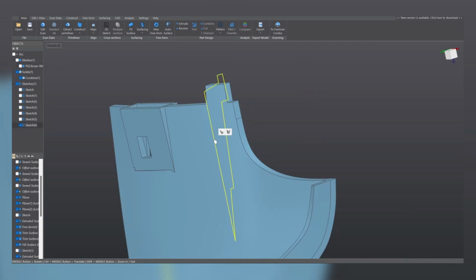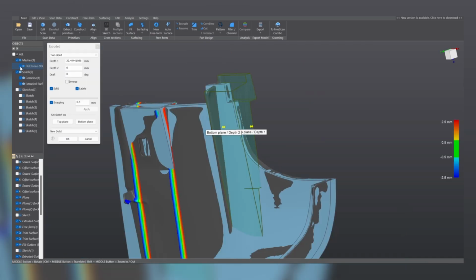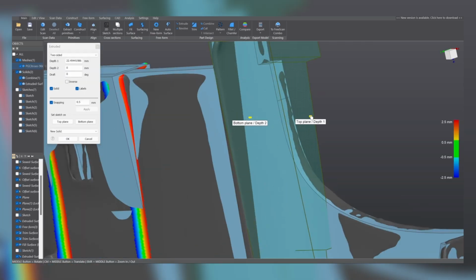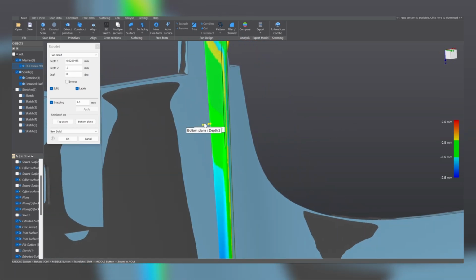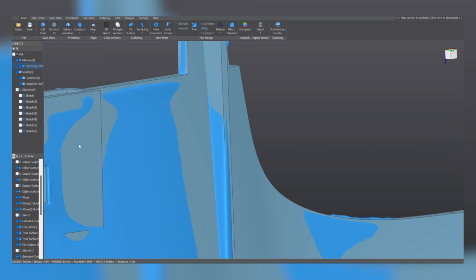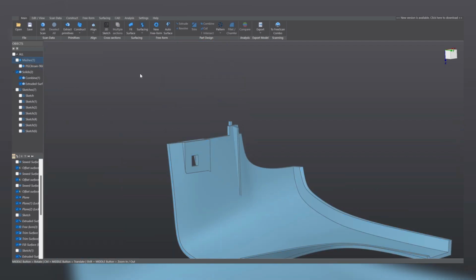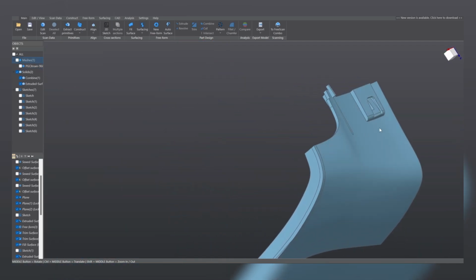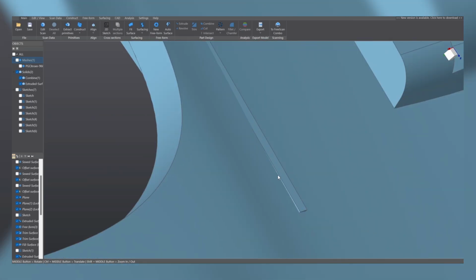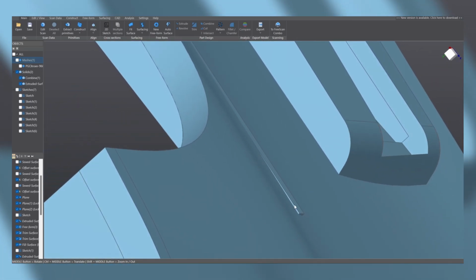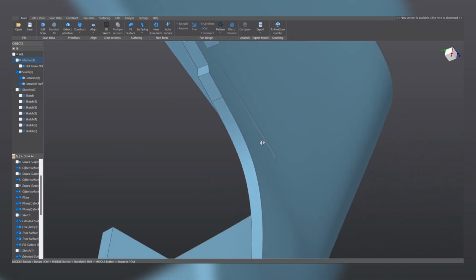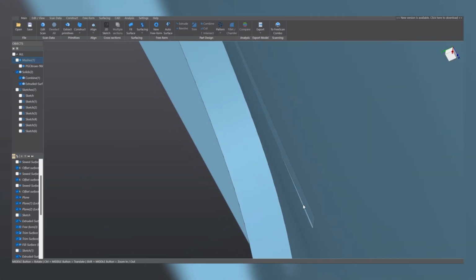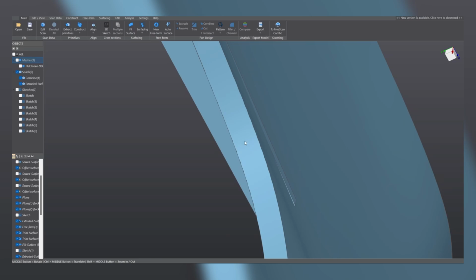Click on OK. Let's extrude it, let's display the mesh, and let's snap on these walls to define the extension of this extrusion. New solid is selected, click on OK. Let's hide the mesh, let's observe the result. Actually, I could correct my sketch a bit because the solid goes beyond, right? It's too large and it goes beyond the original body.